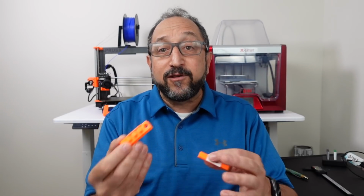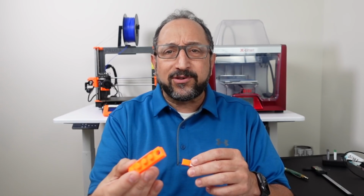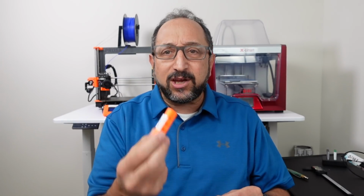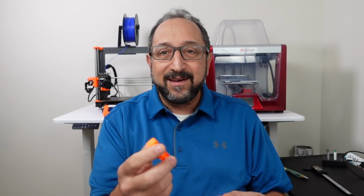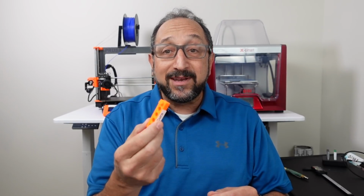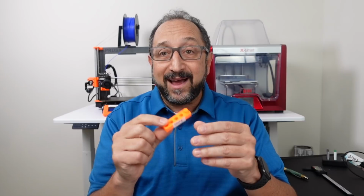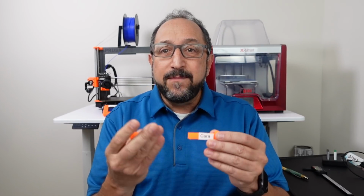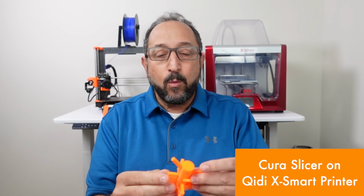So extrusion flow rate, basically, is not as properly calibrated when using the PrusaSlicer defaults with the Quiddy printer as the Cura defaults with the Cura printer. Now, I do know if I print this on the Prusa using the Prusa printer, all the pins come out. And I do know printing this using the Quiddy Slicer, which is a derivative of Cura, on the Quiddy printer, I get the same result as this. So in both cases, once again, could I tune this for perfect prints? Absolutely.